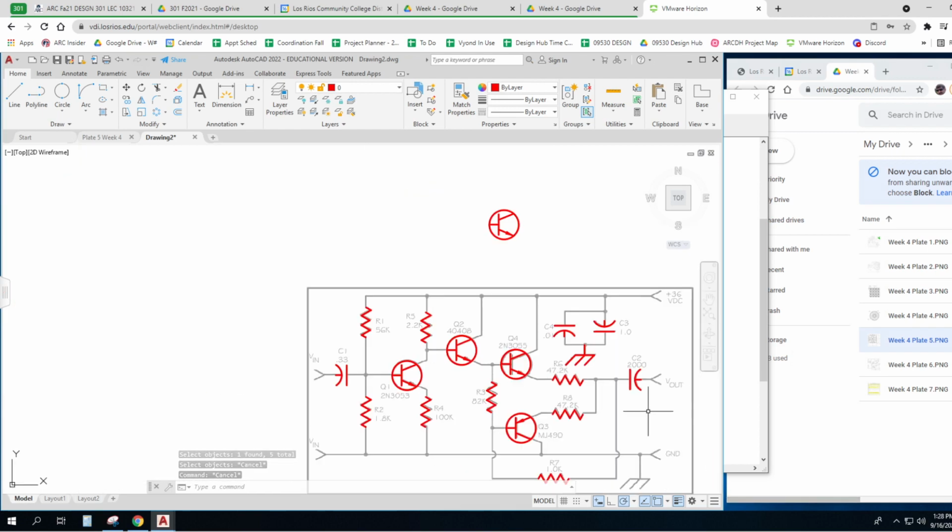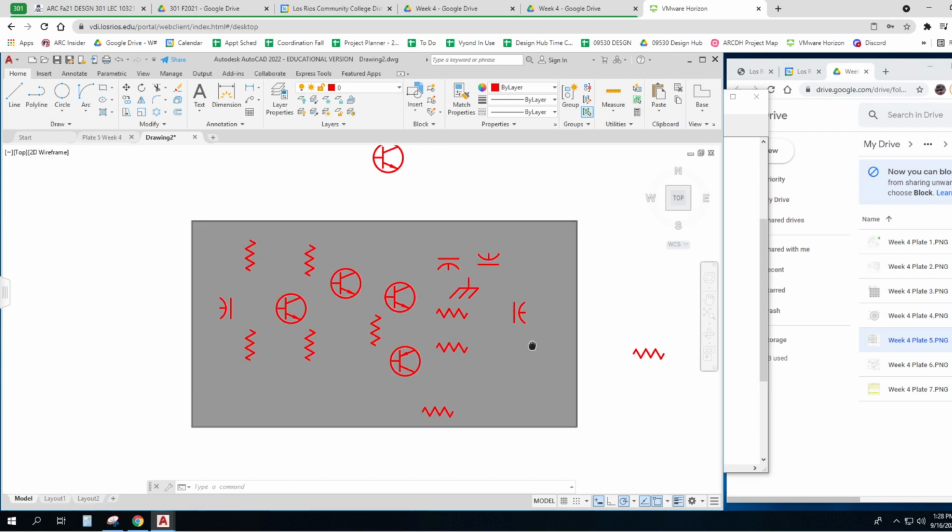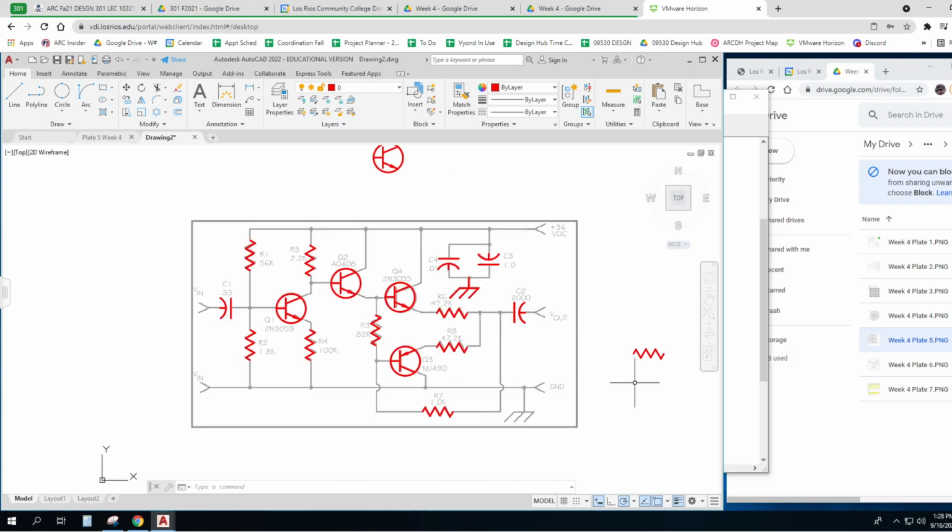So, does it matter when you trace back over a line? For example, you went into the center, then to the left, and then you went back over to the right to complete your line. Does that matter that there's basically a double? It can matter, particularly if you're going to export this drawing to something else, like a machine tool would go over that twice, and you don't want to run your mill twice over the same spot and things like that.